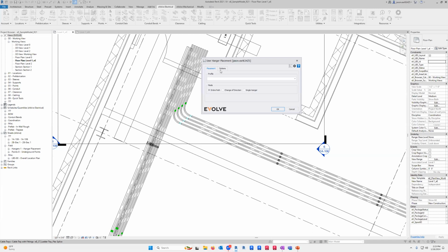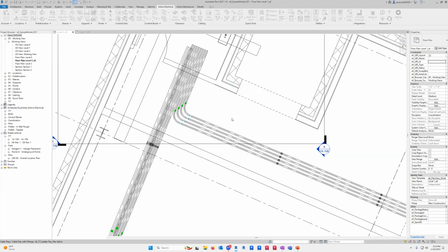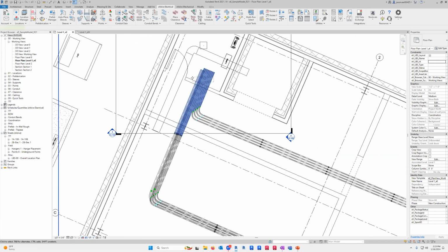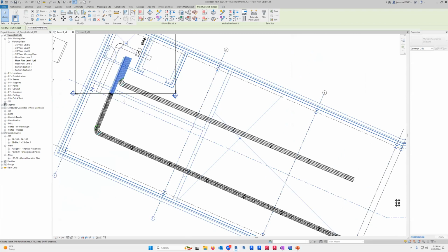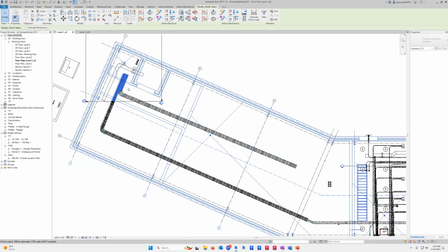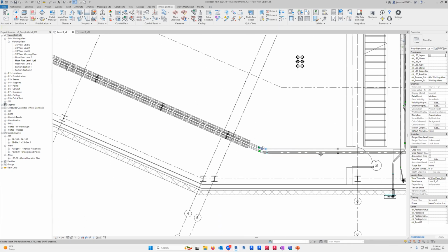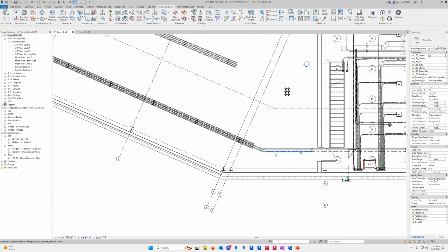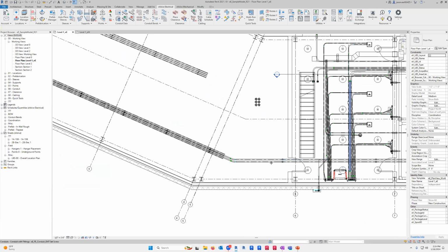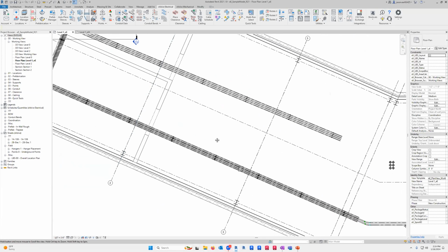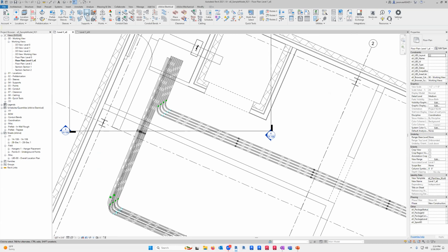And we'll run that. And in my options here, we'll let it attach to nearest structure overhead. We're going to create an unfiltered view this time. And I'm going to use change of direction because, first and foremost, I want to take care of this. Then, okay, that's fine. So that might make me think the entire path is fine. But down here where we stop, we have a change of direction. So we're going to run this, and then hopefully it'll make a little more sense when we run it over here, where that's more of a real world scenario.